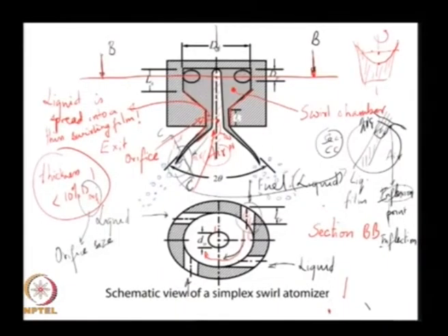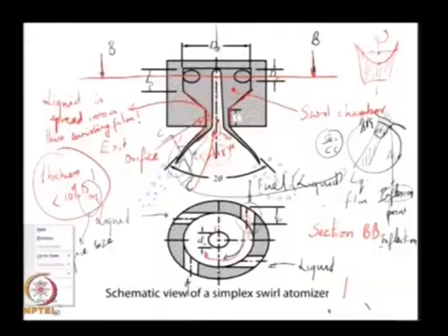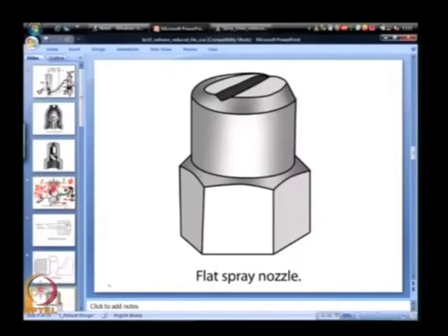And the big advantage of this design, as we discussed in that class, is that the size of the film that is formed is what is going to determine the drop size later on, not the size of the orifice. So, I have now decoupled machining practices from the fluid mechanic performance of the spray nozzle, which is always a good thing. Okay. What we are going to do, just briefly, is to look at one of these spray nozzles in action.